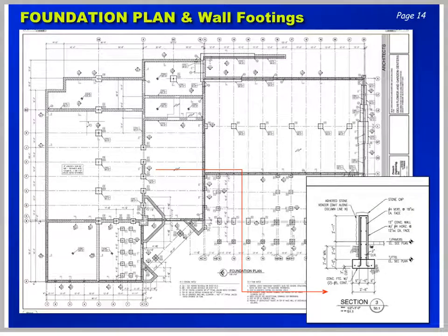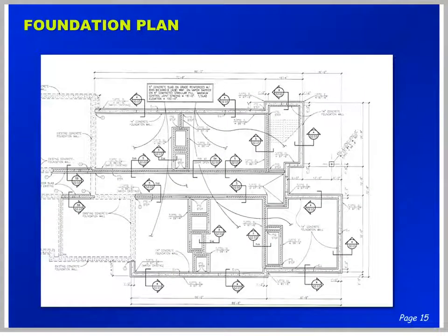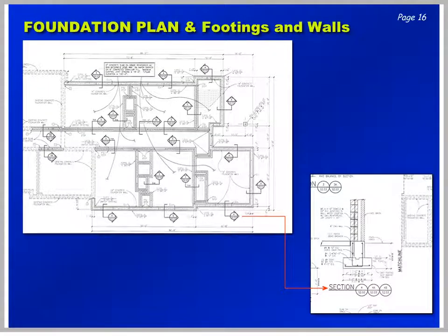Looking a little closer at the foundation plan and a detail, we see a section cut for detail 3 of a short wall and footing. Another example of a foundation plan with section cuts every time the wall changes detail. And to illustrate one of the sections cut in the foundation that is similar in several places, 4, 4A, and 4B. Also note there is a short concrete wall that supports a masonry wall as the building goes up.